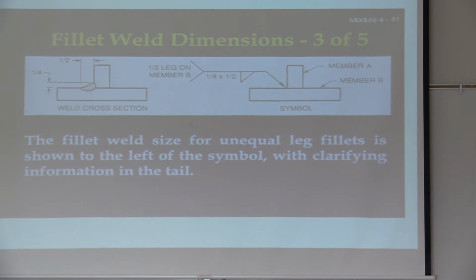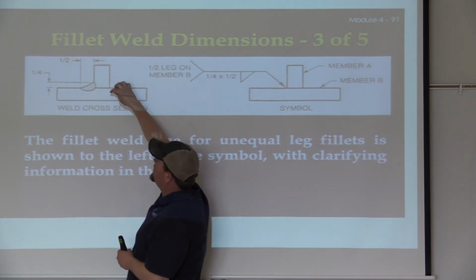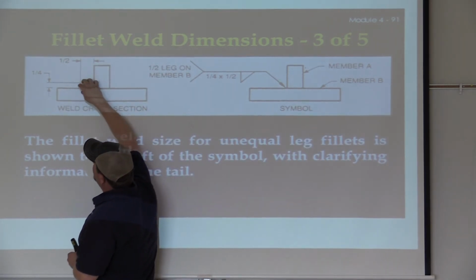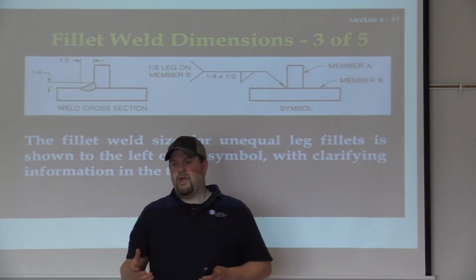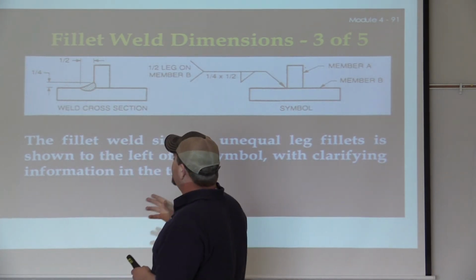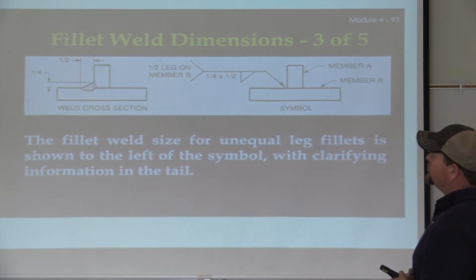It usually happens when you're tying in large or thick equipment, or thick or large members of steel, and then attaching a small piece onto it as well. Because if this is 1/8 inch material, and this is a 1/4 inch weld, then our weak link is our actual material, right? So we need to make sure that we're thinking about that. We always judge the smallest piece.